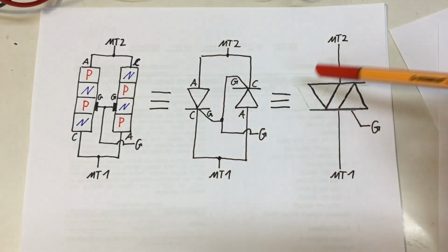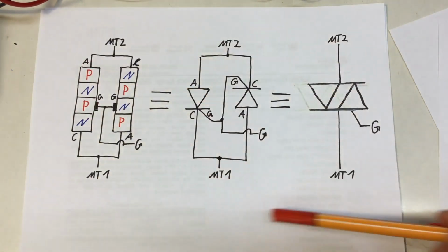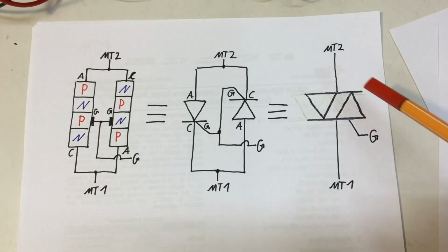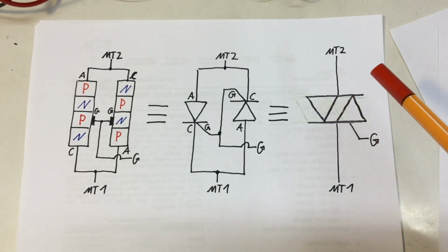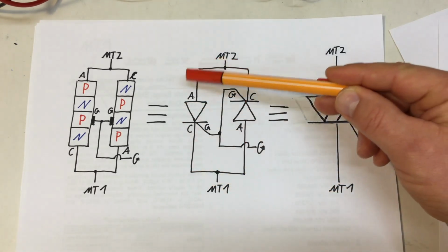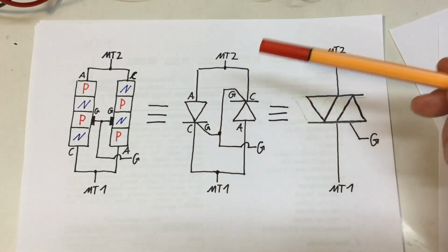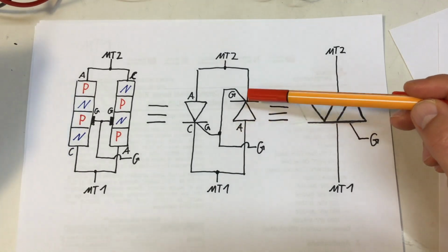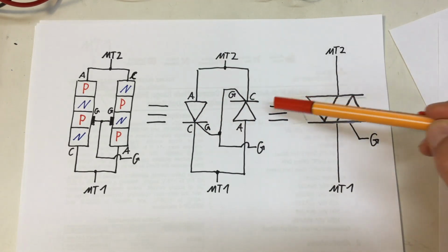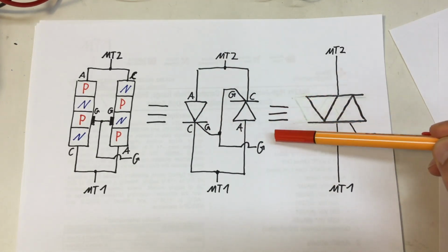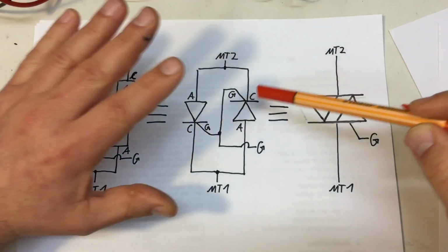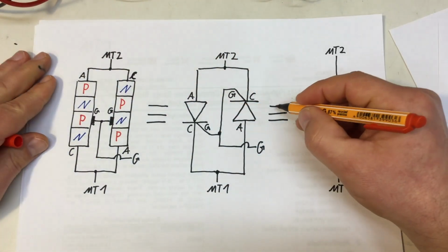So there are several sites out there showing a picture similar to that one here, which I have drawn, stating that a TRIAC is behaving just like two reverse parallel thyristors, or SCRs. I will call them SCRs. Or even stating that this is the equivalent circuit, and they use the equivalent sign, to a TRIAC, which is absolute bullshit.